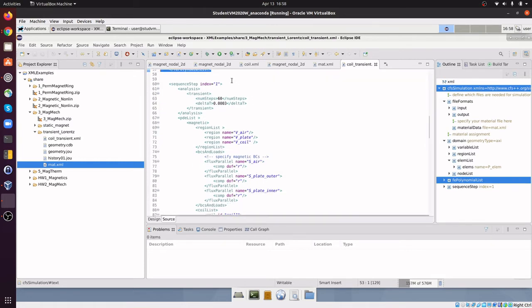It works by default, and we are conducting a transient analysis since we want to investigate the magnetomechanics coupling with the Lorentz force. And as you know, the Lorentz force density is J×B, and in order to have a J, so a current in the plate region, we need eddy currents, and we get these eddy currents with induction, so we need a time-dependent problem, eddy current problem.